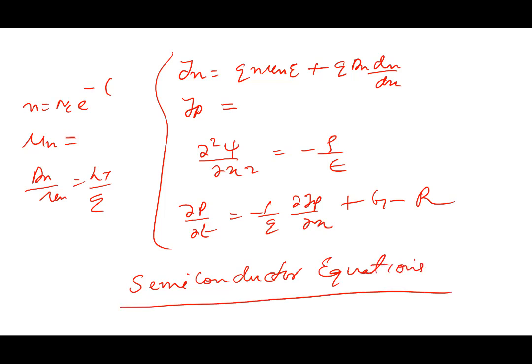These are all the semiconductor equations. For most of the problems, these are all the equations that you need to know. Expressions for current, drift diffusion currents, Poisson's equation, continuity equation. Along with those other things, n equal to Nc, p equal to Nv, mobility, diffusion constants, and things like that. One more thing we need to do is we need to understand this R. How do things recombine? We need a model for R. Generation rate, as I said, depends on the external agency. Whatever is causing generation, it depends on that. So we need to understand R.